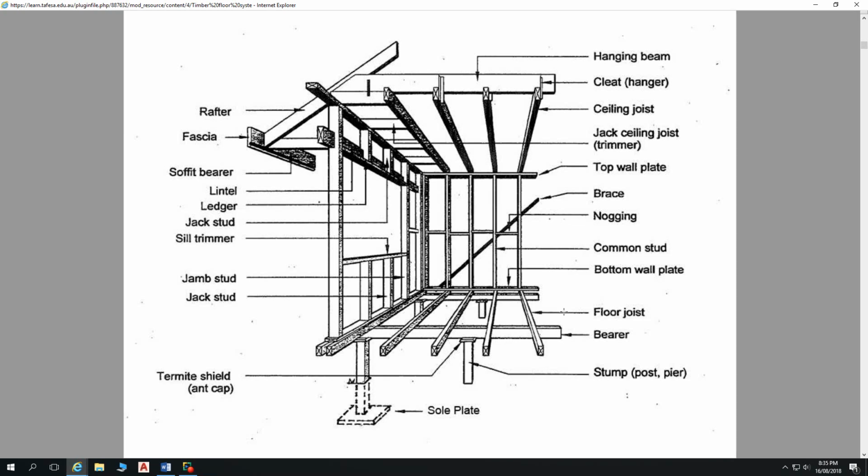We'll go through this fairly quickly. So this is relatively old technology. There's still plenty of buildings built like this. If you think Rivergum Homes, Sarah Homes, whatever, they're still doing a lot of this, and it works fantastically for shacks, for holiday houses, that sort of thing, or for places on undulating sites. So you still see it. Timber stumps, not so much. Typically what you do see more of are concrete blocks glued together, and then various different spacers and ant caps on top to stop termites coming up to eat the framing.